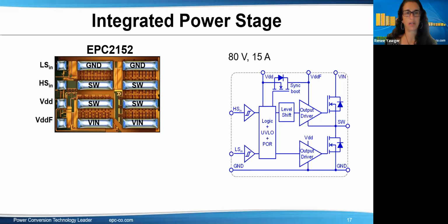Does a GaN driver need Miller clamp protection to avoid shoot-through? Does a GaN FET need Miller capacitance to avoid shoot-through? No. With the Miller capacitance ratio being as it is, the finding was that if you take a transient at the switch node, let me go back over to the schematic here, there's no known transient we found that would be within the specs of the datasheet of the FET that can induce a turn-on of the gate.